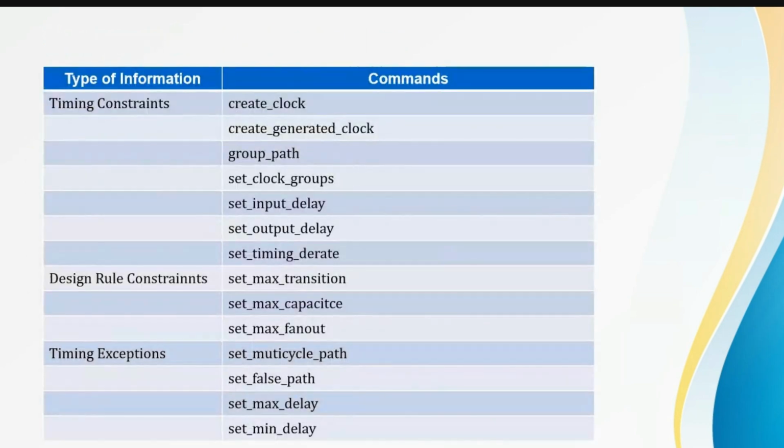So next, these all are the commands which you can see. With the help of these commands only, you will be defining it in the file. In the interview, they will ask these commands. How will you create the clock? How will you generate the clock? How will you set the input delay, output delay, derates, transition time?